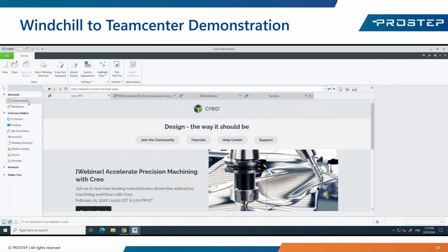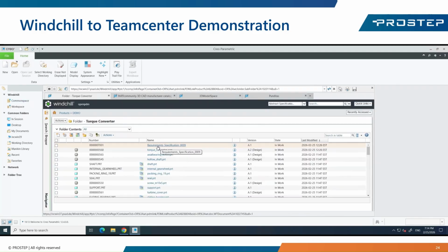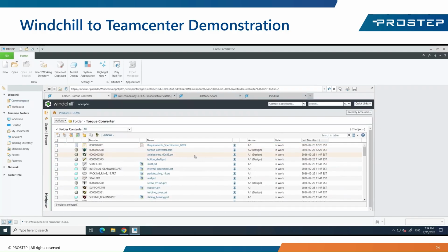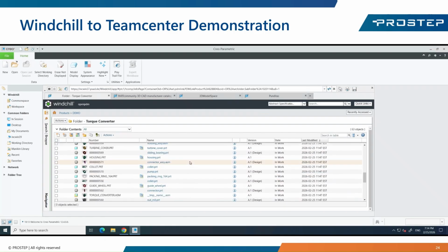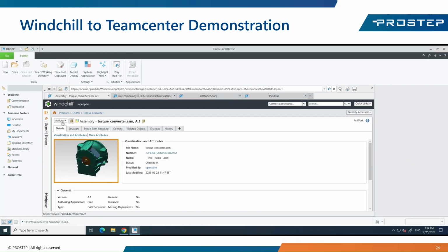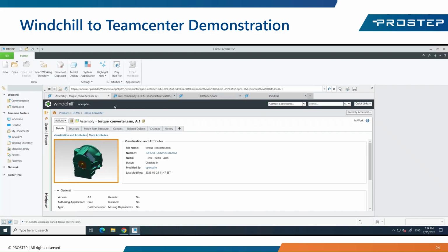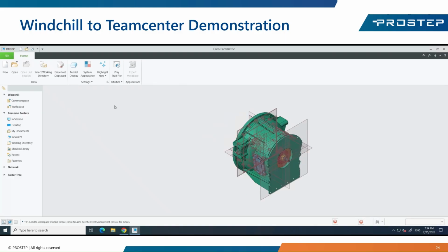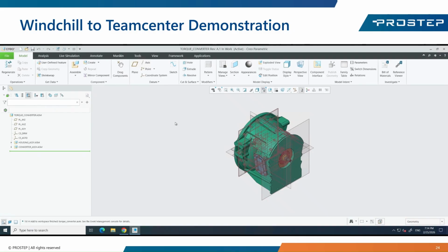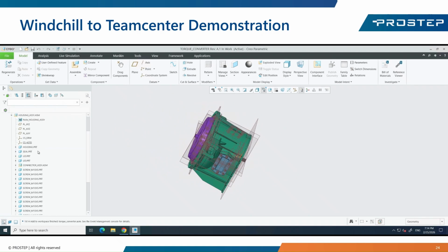like from the Windchill connector. It might be downloading the part data, the BOM data, the WT document data. It's using the Windchill CAD controller that has JLink technology that's exporting the Creo data. So it's doing things like renaming on export and doing it kind of in a proper Windchill way. And then it does some mapping. It maps that part data and BOM into item revision data and BVRs that are needed in Teamcenter.